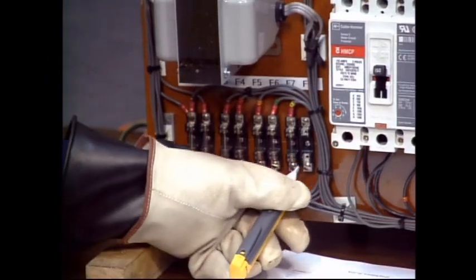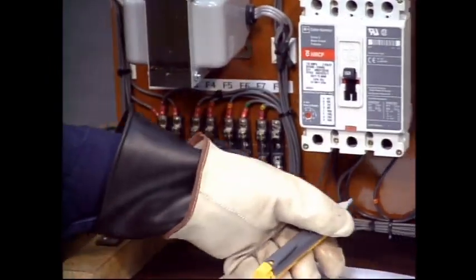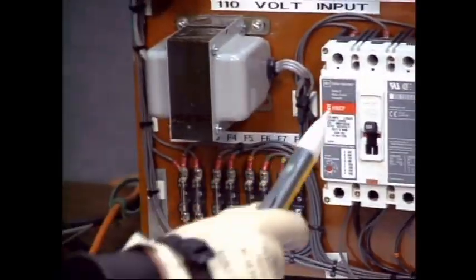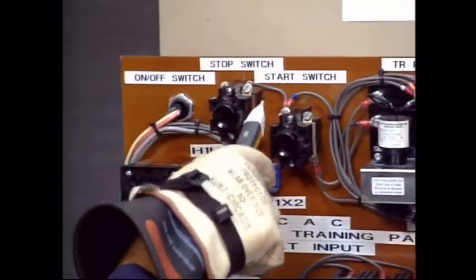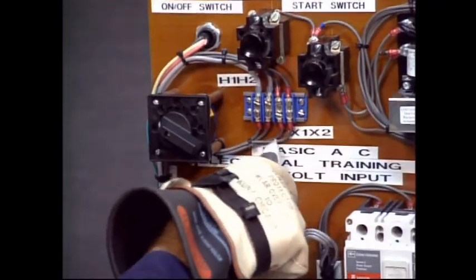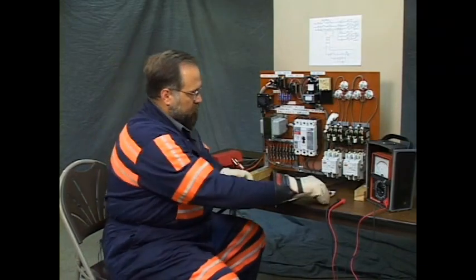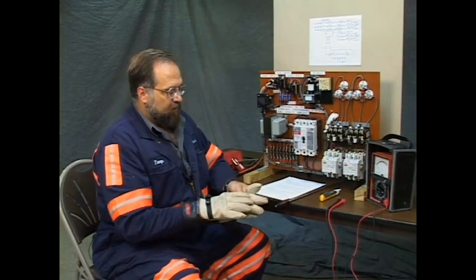Let's see if we can find any electricity on this panel. That intermittent flash is a check circuit for the voltage tester. As long as you have that pulsing flash, that means your voltage detector is working. It doesn't mean it's detecting any electricity though. Okay, we're good. We can take the gloves off and make continuity tests.